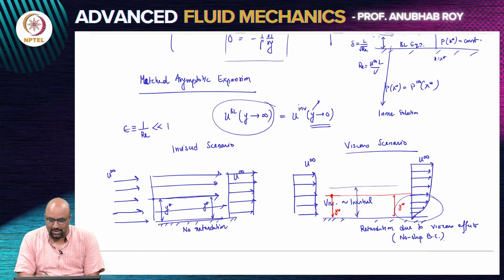That means that the streamline which is entering continues to remain parallel to the bottom plate. I have a bottom plate that is along the x direction and this is my y coordinate. So, I am making a hypothesis that just like the inviscid problem, a streamline that is entering the plate continues to remain parallel to the plate forever. This is my hypothesis. Now, is that correct?